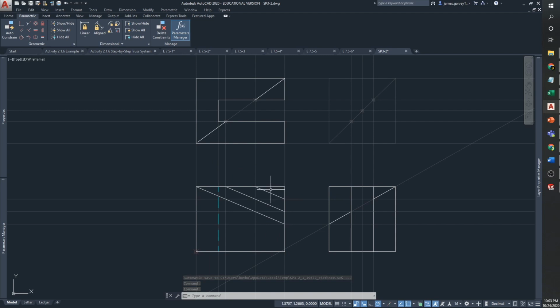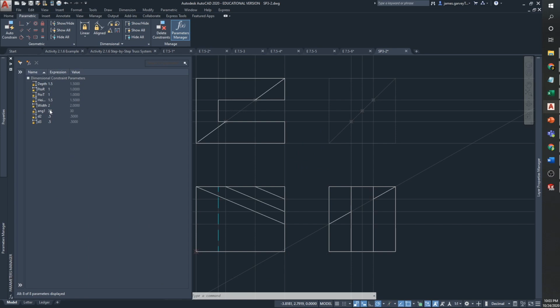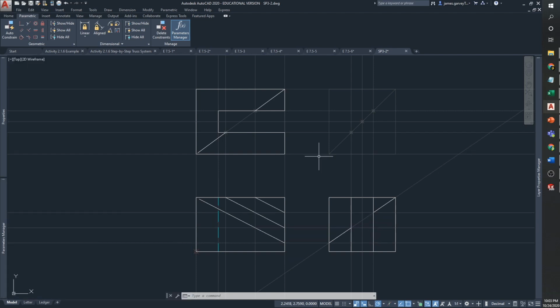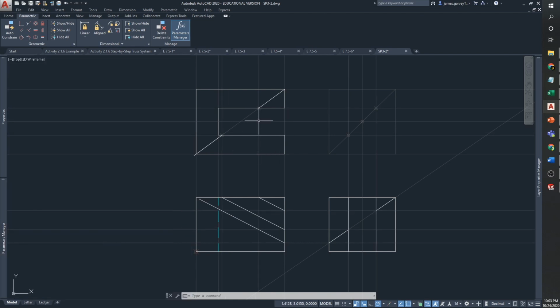It's got two oblique surfaces on it, and we should be able to tie those together. So if I change something like height, let's just change it real quick to 1.25, everything stays there. I can change the angle on it, and that adjusts, we'll say 35. You can see that adjusts the surfaces all correctly. I can maybe change the gap in between. I think that's that one, yep. So let's say 0.625 increases the gap. That also then increases the gap here on the right view.